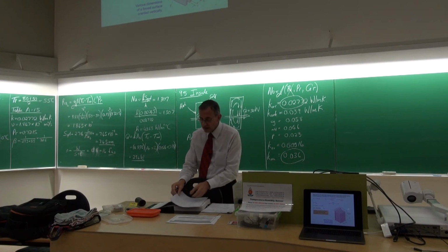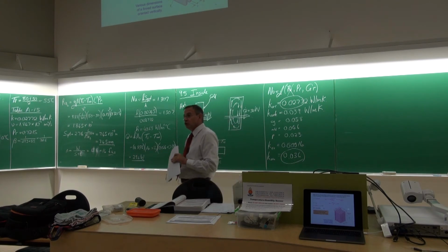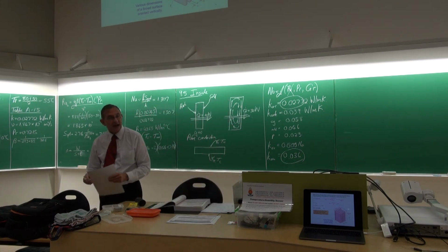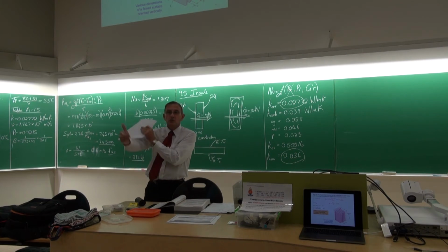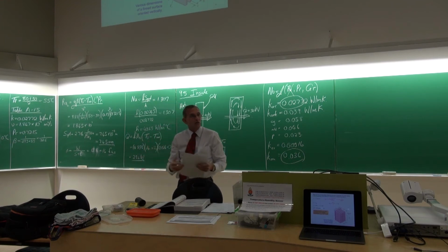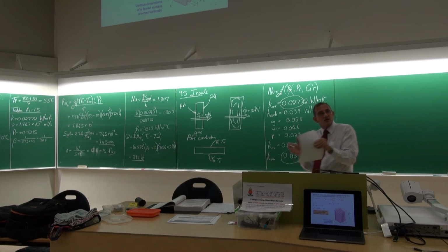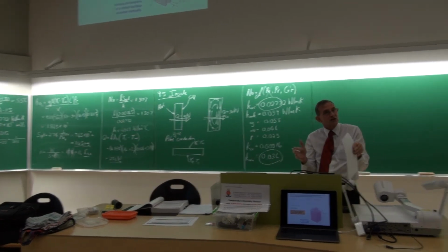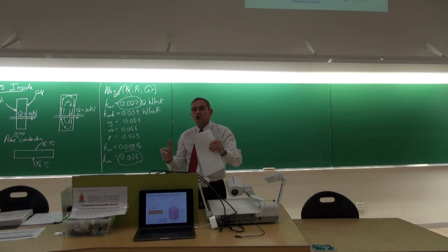Okay. So do not underestimate air as an insulation material. We are very fortunate that air has such a low thermal conductivity. Otherwise, if there was a fire here, you would burn yourself. The air is a natural insulation material between you and the fire. And the result of that would be that the only heat transfer that you're going to get in most cases is the radiation heat transfer. It is not going to be the conduction or the convection.